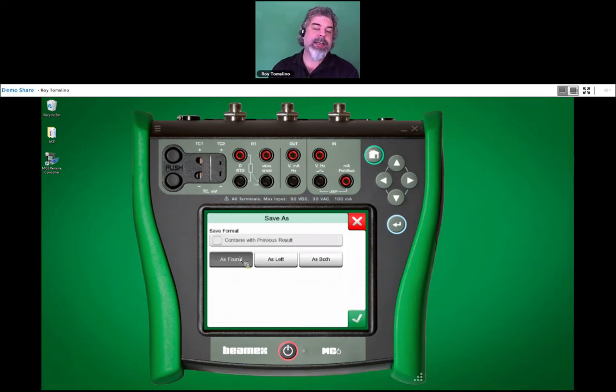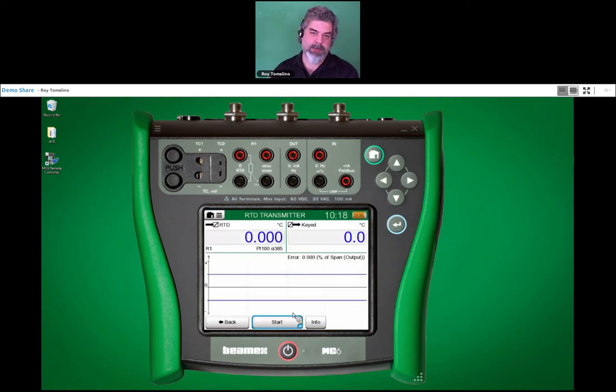All right, and we'll save this guy. As long as it's done and complete, we can save it as both, as found and as left. So I'll choose save as both, and I'll hit the check mark, and I'm done. So my test is complete. I've got a test result for the entire loop calibration, and let me go back here.